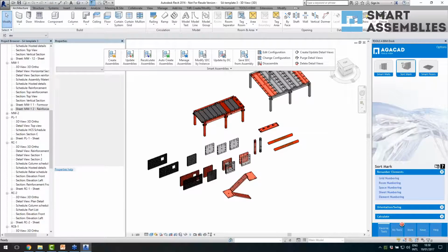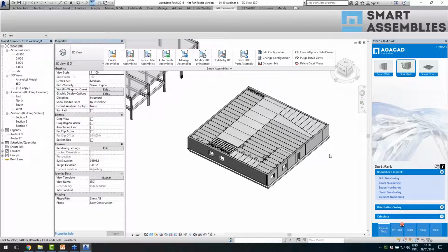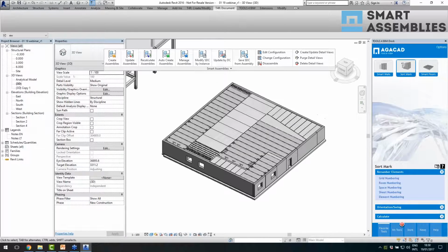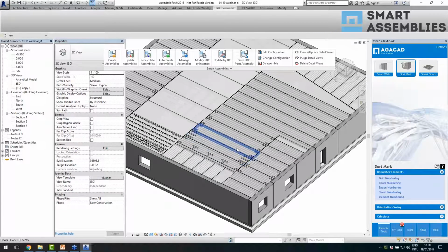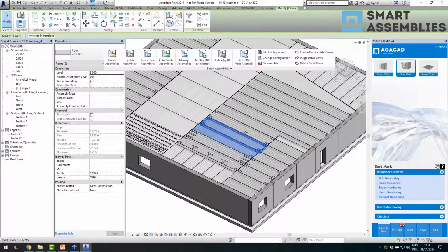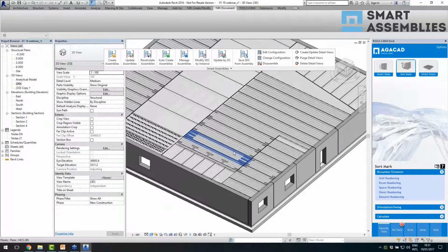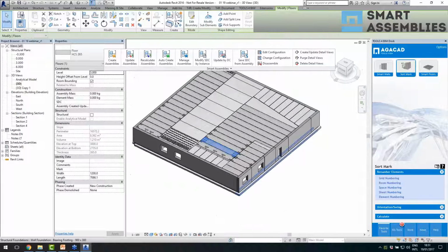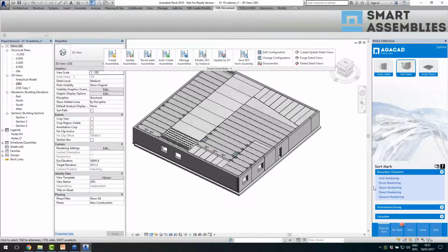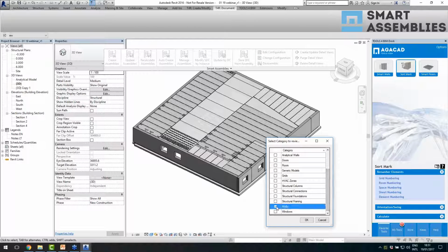And now in that project, I will use the template project sheets to create my sheets on this project. So let me select a few of the floors, let's say like this, and create assemblies. So now in Revit, you would have only one assembly now of 3. Sorry, I don't have the names or mark values. Did I miss to? Okay, I just renumbered just walls and columns.